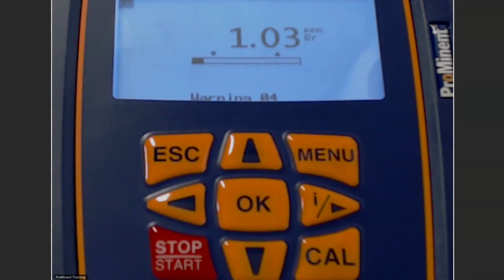With option 2, I can bring in a couple of different signals, and most often those signals have an effect on the first channel, whether it's changing the reading, which is what we're going to focus on here for pH correction, or maybe changing the way the control output is controlling the application.